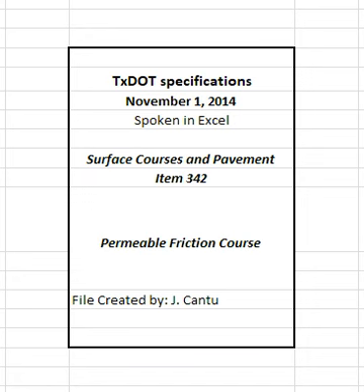4.3.5 Placement and Compaction. For placement and compaction, include proposed agenda for mandatory pre-paving meeting, including date and location. Proposed paving plan, for example paving widths, joint offsets, and lift thicknesses. Type and application method for release agents in the paver and unrollers, shovels, lutes, and other utensils. Procedures for the transfer of mixture into the paver, while avoiding segregation and preventing material spillage. Process to balance production, delivery, paving, and compaction to achieve continuous placement operations and good ride quality.